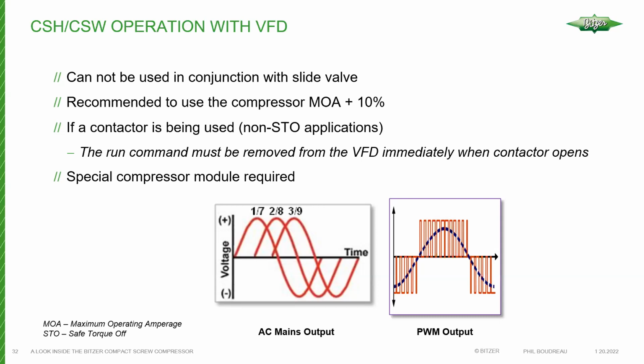And what'll happen is you're going to start to run into alarms. You could see an overload alarm, a low bus voltage alarm. That's the most common one. And also, you're putting a lot of strain on these components known as metal oxide varistors at the inputs to the drives. They can take a bit of abuse, a few cycles of this, but if you do this repetitively, you're eventually going to take those out, and then the drive's got to be either repaired or replaced.